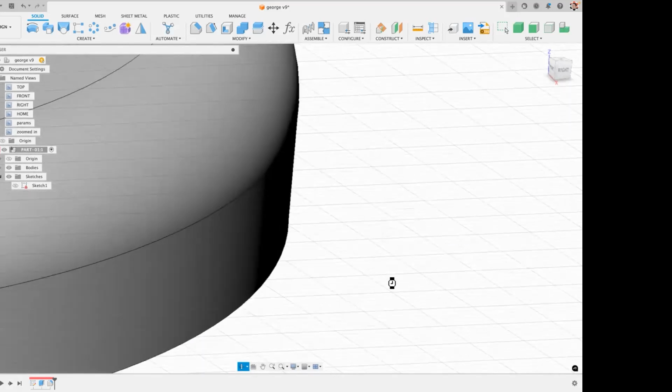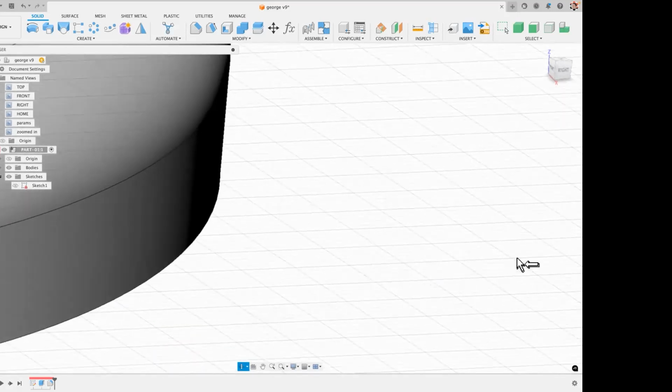Okay. There you go. Now, lastly, if you radially go out any direction, this stuff is the same in any direction because it's a circle. If you keep going out, it's going to change yet again. And now you get an arrow pointing at the cursor. That's cancel. Click it now, and you've just put down your hammer. Okay, so I'm just back to a normal cursor now. That now you're a picker. You're in the picker mode.